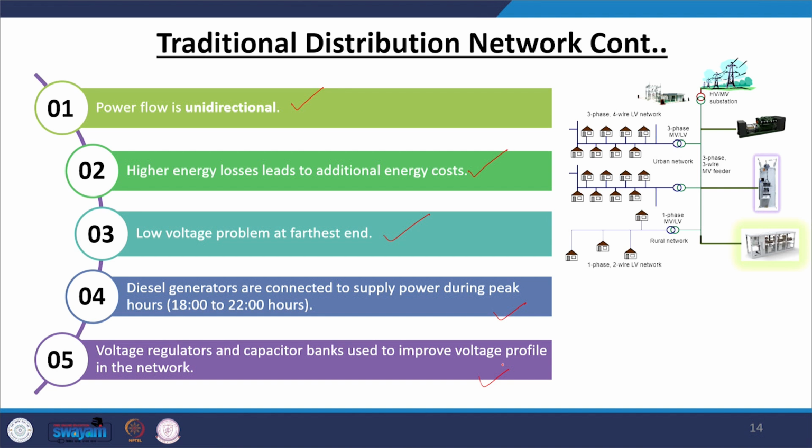I do not know about any part of the rural villages, but we all might have experienced a little bit of voltage fluctuation during evening hours. Because in the evening hours the load is so high, the voltage actually starts dropping. Am I right? So we normally don't experience close to 230 volts. It may sometimes be 225 and as bad as 220. So my lighting system sometimes flickers if it is an LED system, or it is dimmed with a supply which is below the required voltage.